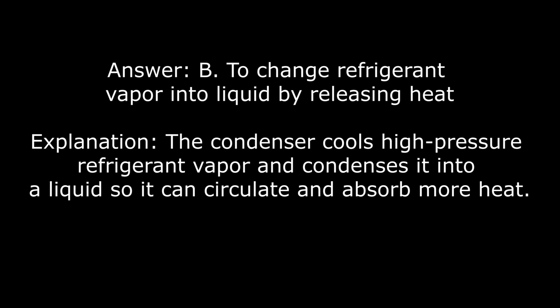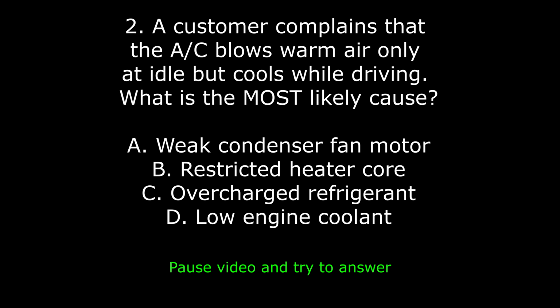Explanation: the condenser cools high-pressure refrigerant vapor and condenses it into a liquid so it can circulate and absorb more heat. 2. A customer complains that the AC blows warm air only at idle but cools while driving. What is the most likely cause? A. Weak condenser fan motor. B. Restricted heater core. C. Overcharged refrigerant. Or D. Low engine coolant.